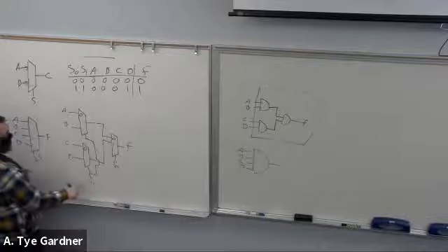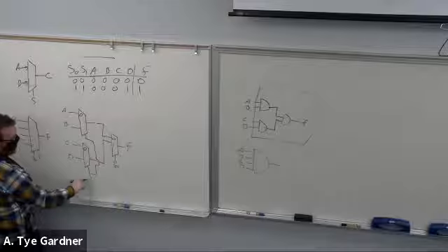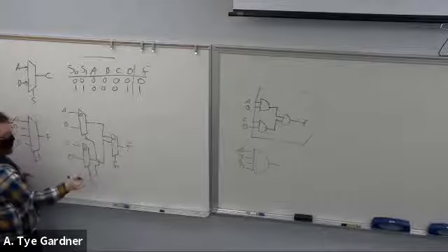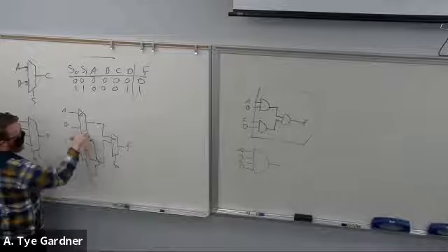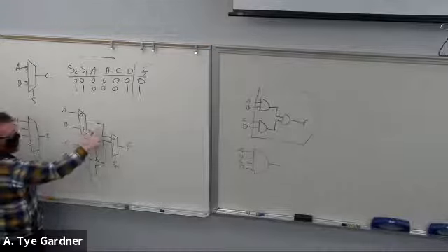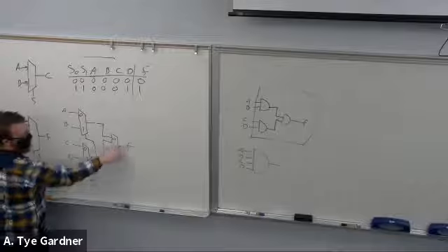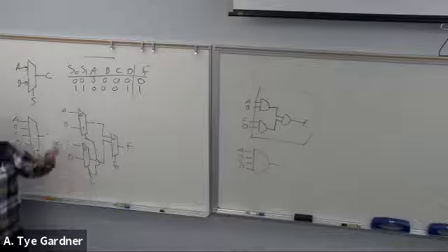That way, when I do 0, 0, 0, 1, right? So then if I have 0, 1, where S1 is 1, then I would get B here because S1 is 1, and then still 0 on the F. Now, you can actually make it work that way just fine, just depending on how you define your select inputs.